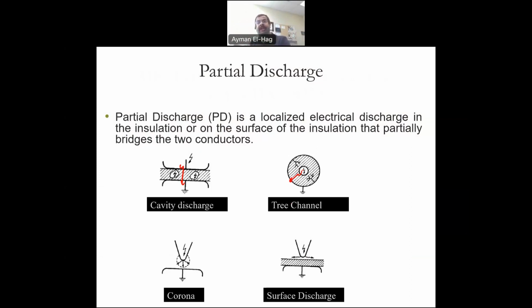Now, when you manufacture the equipment, we measure the partial discharge at the premises of the manufacturer. And when we install them and when they are on the system, then often we go and do some sort of random check and try to measure the partial discharge in the field.